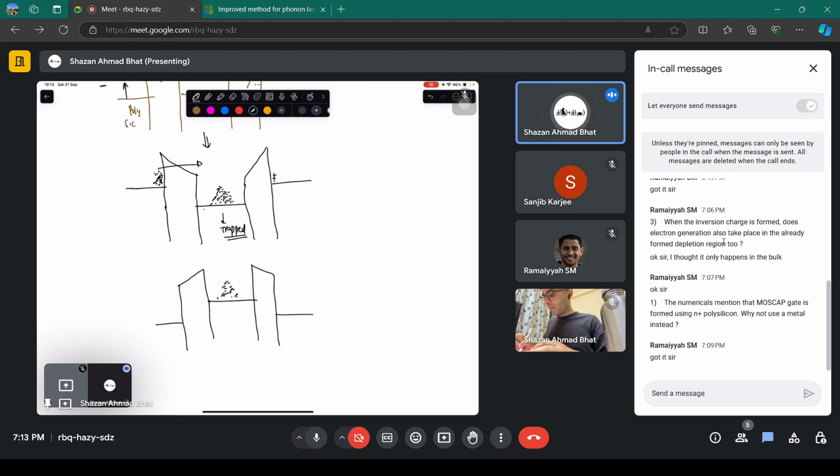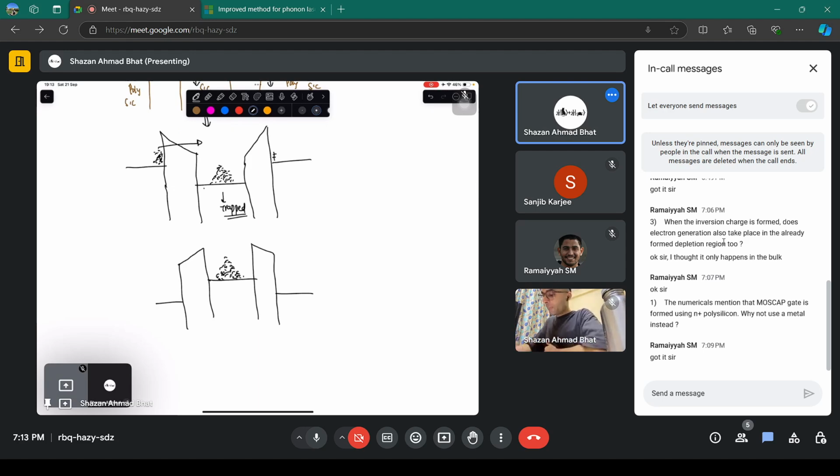I just want to give you the flavor of it, from an application point of view. Don't think of the electrostatics right here. So the electrons tunnel through the oxide, they stay here in this semiconductor, pile up, and this is actually the memory. You have created a memory, you have stored electrons.